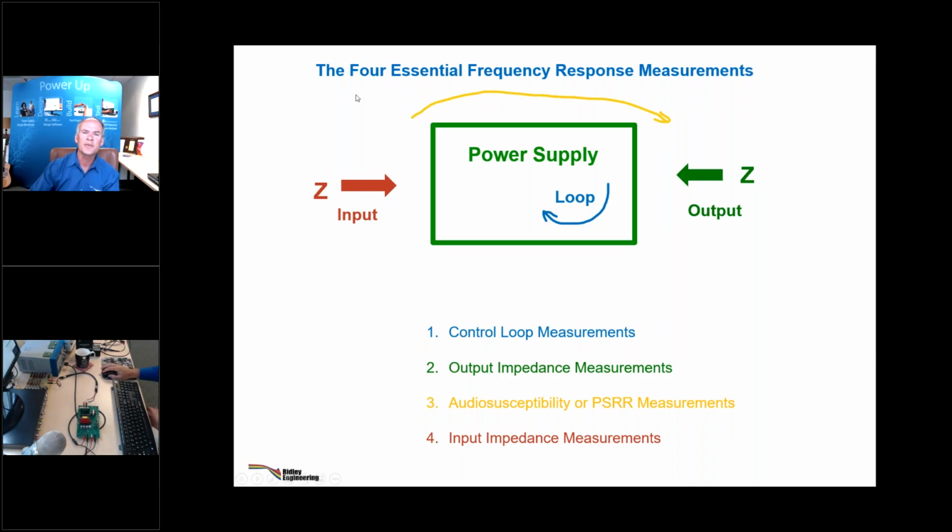And if the input impedance was high enough and the output impedance was low enough, they could say, well, it's not going to react. This is Middlebrook's input filter problem or extra element theorem, whatever you want to call it. If you make it a low output impedance, high input impedance, that block is kind of impervious to whatever you might load it with or provide it with. So that was the whole reason to measure this and this.